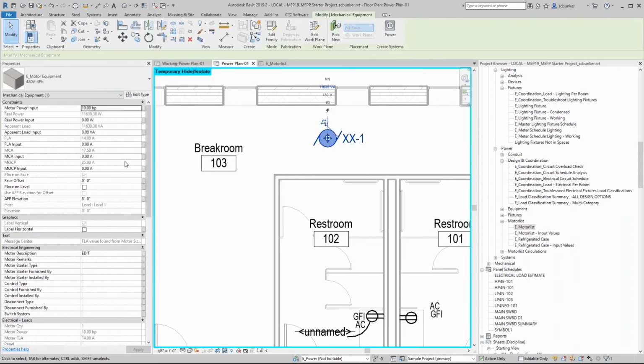All right. This looked up a 10 horsepower, 480 volt motor from the NEC tables at the back of Article 430. And it looked up the FLA and put it right here. So 14 amps. If you look in the table in Article 430, you should find 14 amps for 10 horse at 480. And then from that, it will calculate all of these other values.